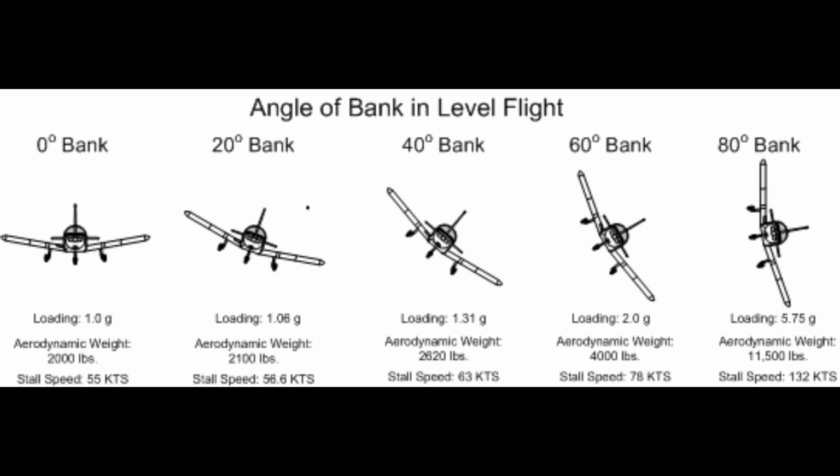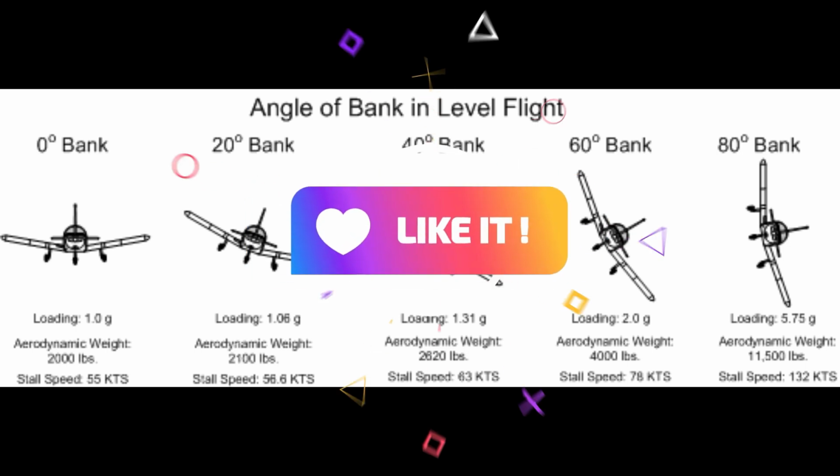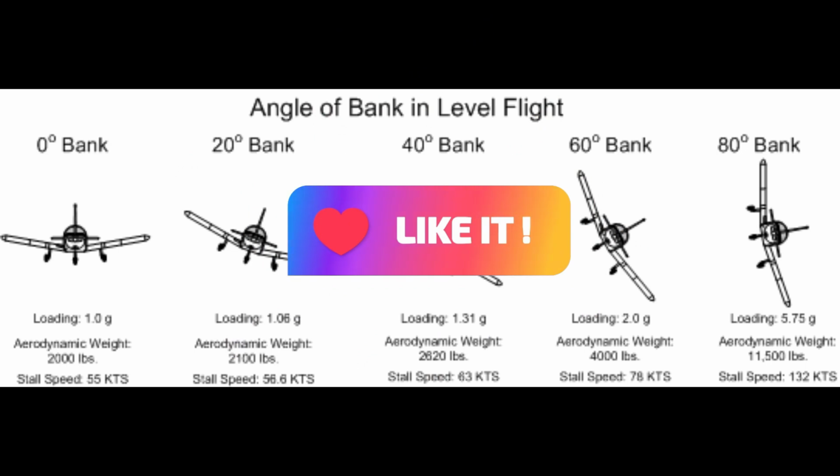There is an upward graduation in load factor with the increasing severity of maneuvers. The category system provides for maximum utility of an aircraft. If normal operation alone is intended, the required load factor, and consequently the weight of the aircraft, is less than if the aircraft is to be employed in training or acrobatic maneuvers, as they result in higher maneuvering loads.